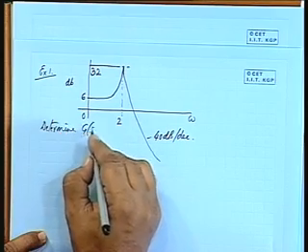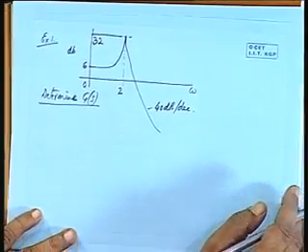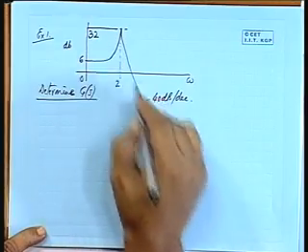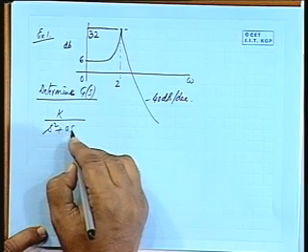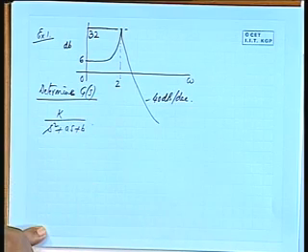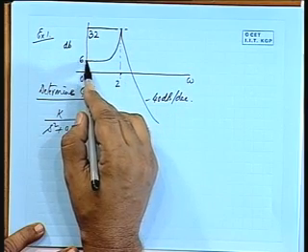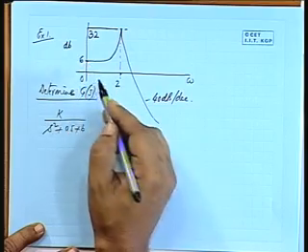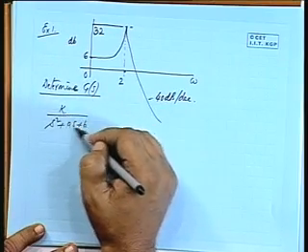Mind you, we are making approximate estimates of such functions GS. So let GS be a function of this kind, k by s squared plus as plus b. Is that all right? Let this be GS. Could you suggest from these values, omega equal to 2, at DC, that is omega very very small, this is 6, and at the peak it is 32.